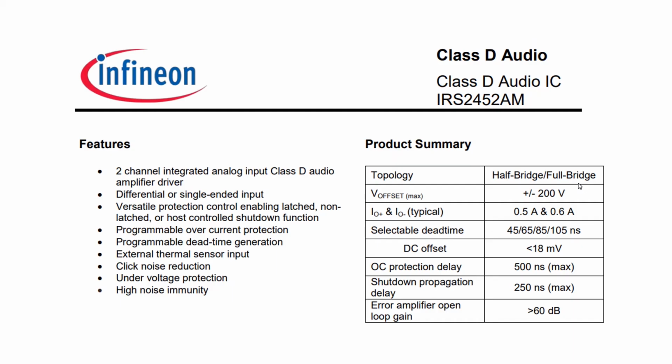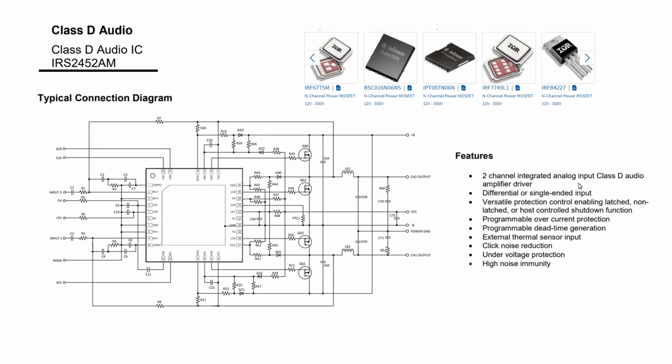And this is a gate driver for high power solutions with rail voltage up to plus minus 200 volts. You can build high quality kilowatt capable designs. My guess is that some ICEpower kilowatt capable designs are based on this chipset. But don't forget about the power supply. For kilowatt designs, a lot of costs are associated with the power supply and effective protection circuits.